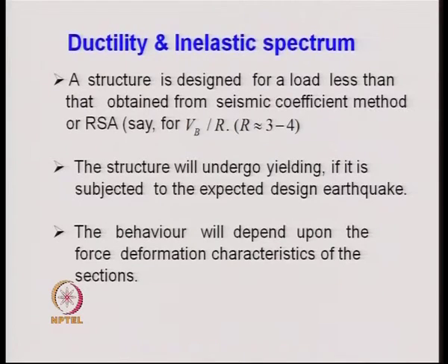Ductility detailing of reinforcement is a very crucial issue in the structural drawings. At every joint, these structures must be detailed properly for earthquake, and so far as reinforced concrete structures are concerned, there are guidelines given in all codes on how one can provide adequate ductility by way of reinforcement detailing.